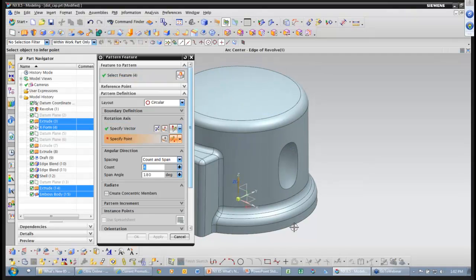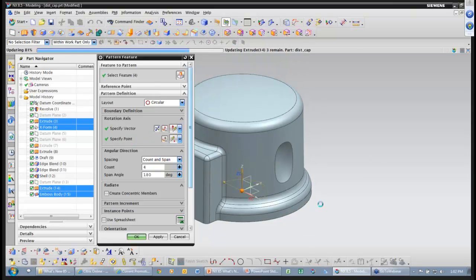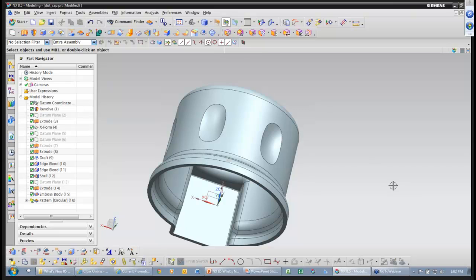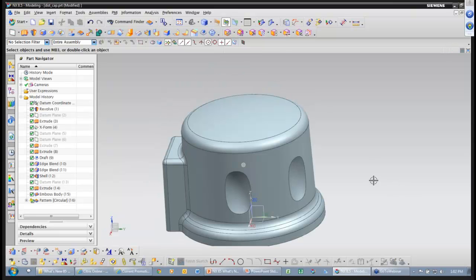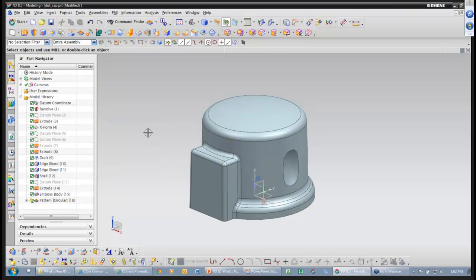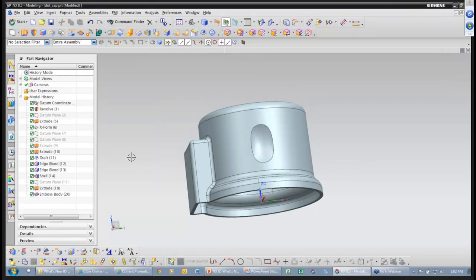We'll do a circular pattern about the center. Put 4 of those halfway around. So obviously we just pattern those to maintain that shape. Actually pattern my other feature down there too. Just a couple things. I want to show you some finished examples of, actually we've got to unite yet. I apologize for that. Let me blow that pattern away for a second.